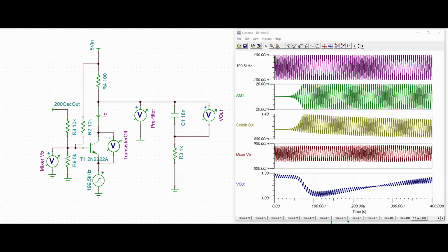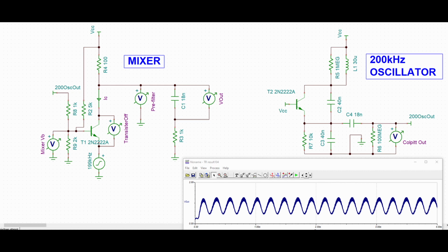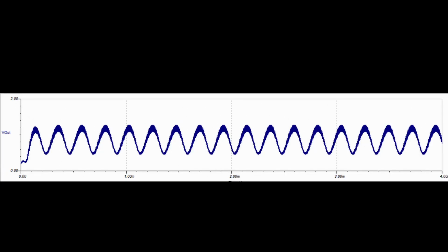So what I did instead was keep the oscillator connected to ground, but connect its output to the rest of the network using various resistors to get it biased at the right point. I then twiddled with the resistor values a bit to increase the amplitude of the final output, and then I had the implementation of the oscillator sorted.